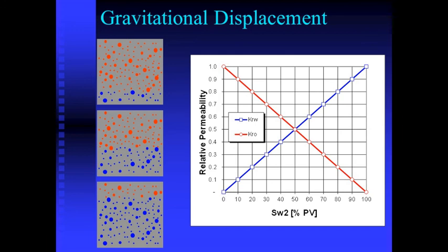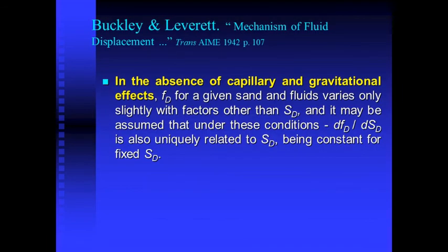In this case, it is easy to explain this characteristic, since, as the water level rises, the increase in water saturation matches the simultaneous flooding of small, medium, and large diameter pores. Under these conditions, higher water saturation implies a linear increase in water conduction capacity, and that situation generates the Rel Perm curves we are seeing.